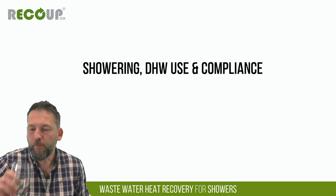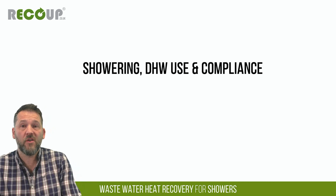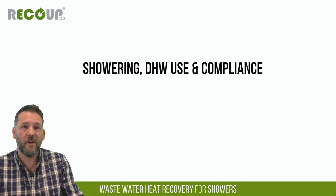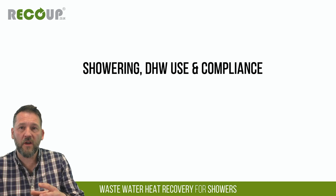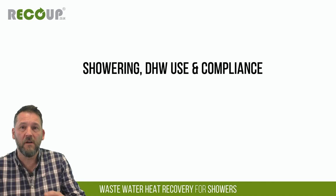One around hard water and scaling. Yeah, generally not an issue. Because we're only preheating that cold water up to 25, 28 degrees, we're not getting much hotter than that on the cold side. So generally scaling isn't an issue. Realistically, those temperatures aren't much more than the allowable cold water mains temperature in summer, allowed by most water companies. So it isn't really an issue for scaling.